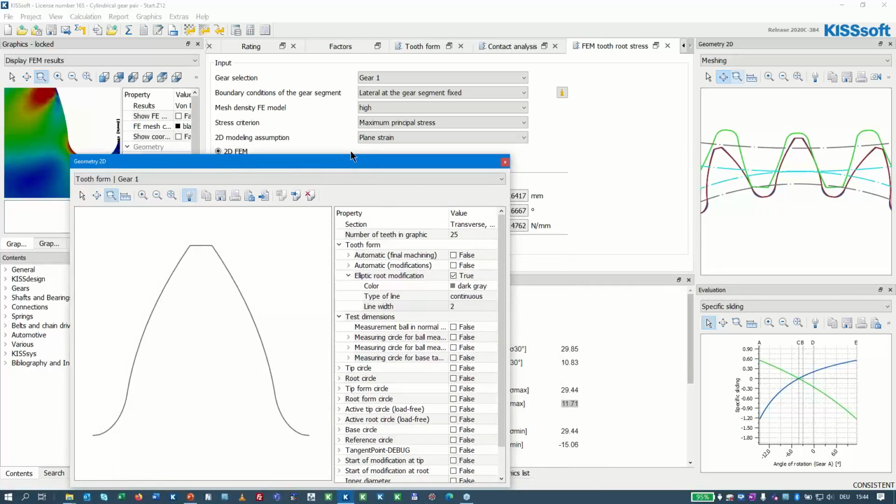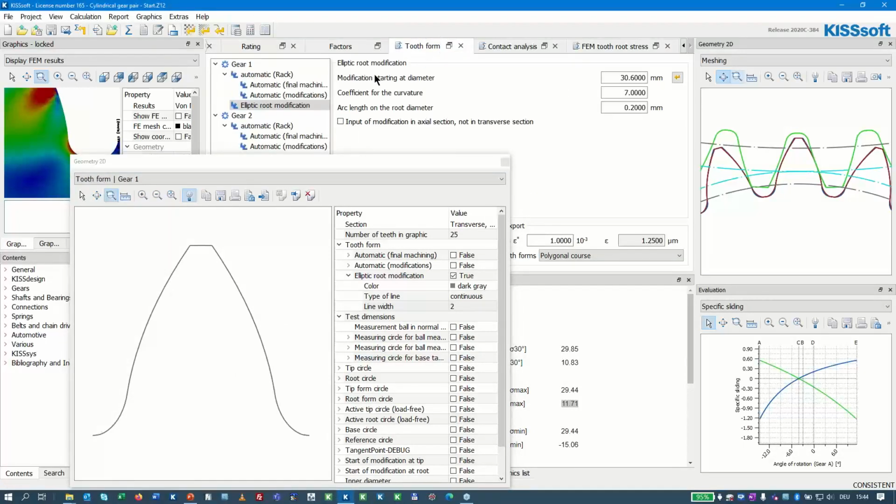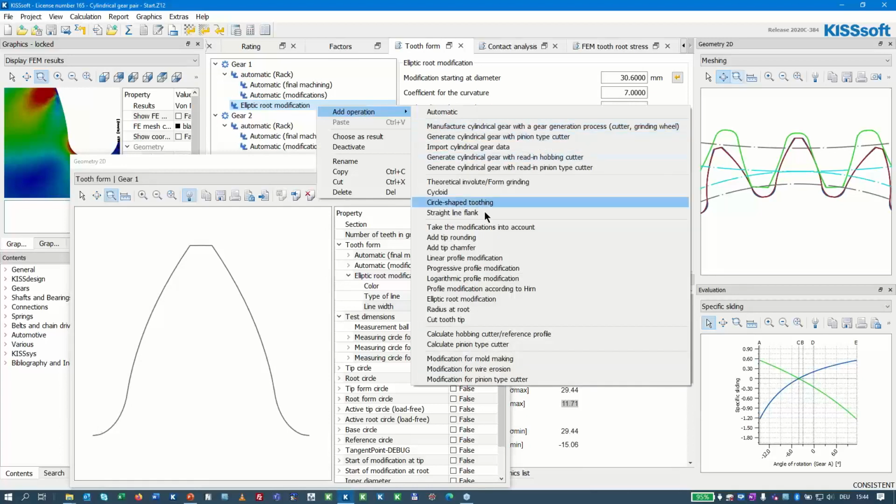To consider this process again, I need to use the tooth form, and first I define that I want to calculate what is the shape of the cavity that generates the desired gear. The difference being once you remove the gear from the cavity, it will shrink. This means the cavity has to be larger than the desired gear.